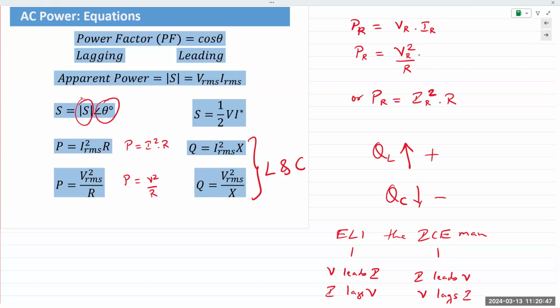In real life, all power is just power. It's not negative or positive anyway. But even mathematically speaking, real power is always positive. And the question being asked was referred to real power. And in this sense, real power refers to the resistive power, P. So P is described as real power. Q is described as reactive power. But make no mistake, reactive power is also real in real life. It can get confusing.